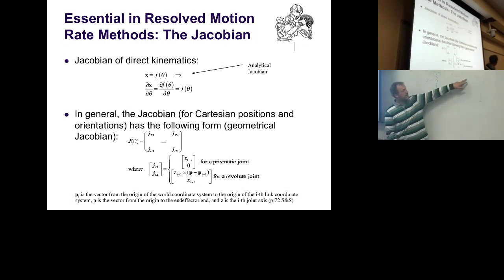Getting the Jacobian components with respect to positions is actually straightforward. So if you just differentiate, literally, we know how to write down with homogeneous transformation matrices, for instance, our transformation from world to any vector space. But not our Jacobian, sorry, our function f. It's just a multiplication of homogeneous transformation matrices. When you do this differentiation, you get these first two rows.